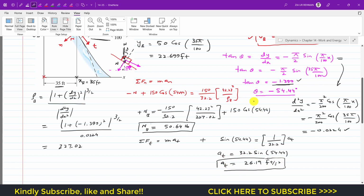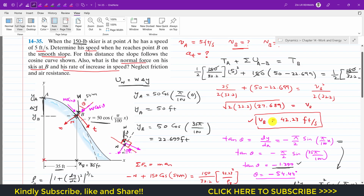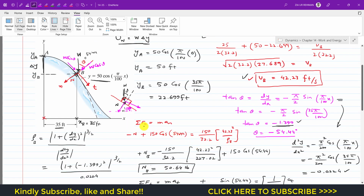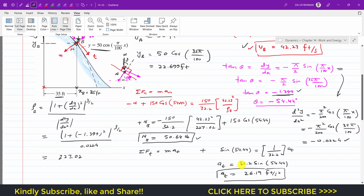So we have determined the velocity of the skier at point B, which is 42.23. We have determined it from the work energy principle. Then we have determined N_B using the summation of forces along n. So that gives us 50.64, and then we have determined the tangential acceleration, the increase in the speed, by applying the summation of forces along the tangential axis. So this is the solution of this particular problem.